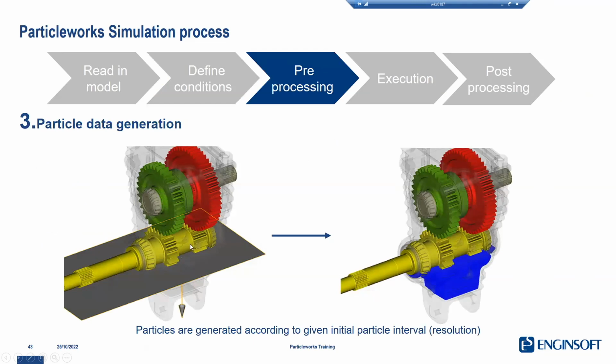Then you would have the pre-processing. In the pre-processing, for instance, here we see that the fluid is initialized below a certain filling level, okay? So during the preparation, we might want to define a filling level, and automatically the software will understand the inner region of the casing and will create the fluid, as you can see here, during the pre-processing. In the pre-processing, the mesh at the interface, so the solid, will be discretized automatically. So basically, starting from the STL, we have a discretization with a Cartesian grid with a specific grid size of the walls. And this is again done automatically, okay?